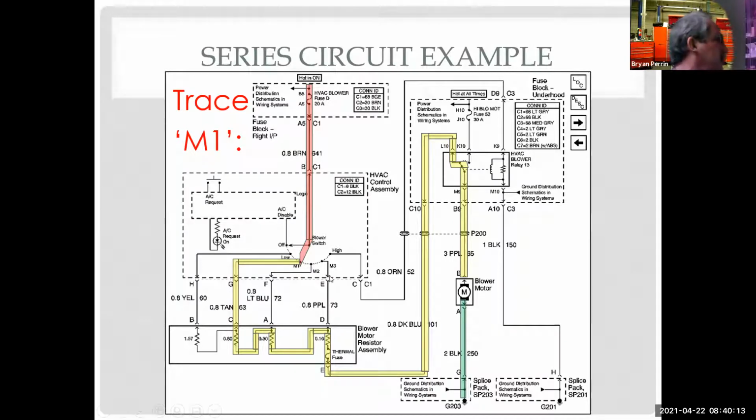Because people don't understand that even though I'm moving my switch, we have these open circuits where battery voltage potential is going to be able to be seen back on the back side of that. And this is what makes electricity confusing for people when they're trying to fix it. It's like, why do I have power at all four places when I'm on low? And they know the power comes from the switch, so the next thing you know, the car gets a new switch. Well, wait a minute. All we have is voltage potential coming from here back through a load on an open parallel circuit.